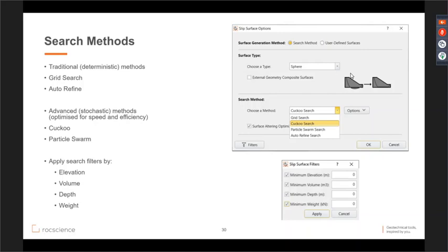For a wedge failure consisting of more than one weak plane, is it practical to include multiple planes of weak surfaces? There are multiple ways that you can model wedge failures within Slide3. RocScience has SWedge as well, where you can model up to 5 release planes.